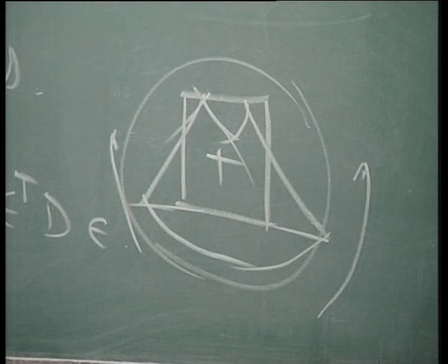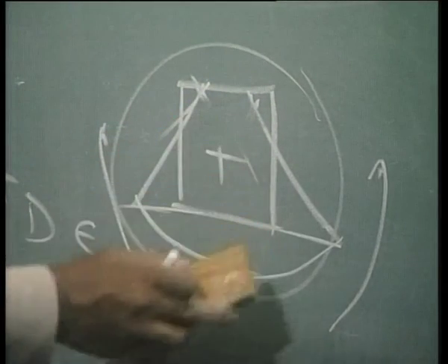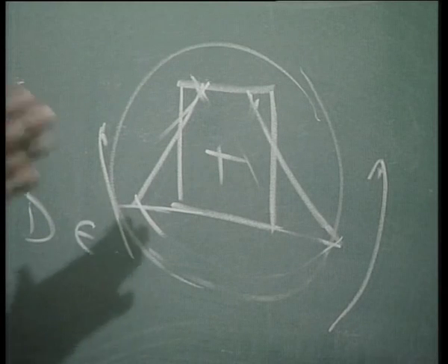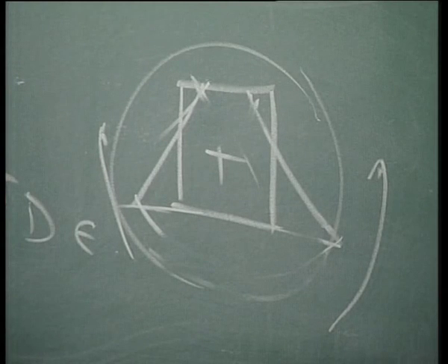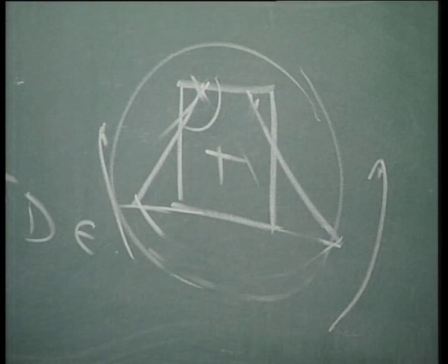But this kind of deformation is not possible, and hence we get something like this. That's another issue, which I wanted to point out, and nevertheless it's also very important. So now what happens because of this? You are introducing shear, because this angle is no more our famous 90 degrees. People call this by different names, and this is one of the drawbacks, what they call parasitic shear.